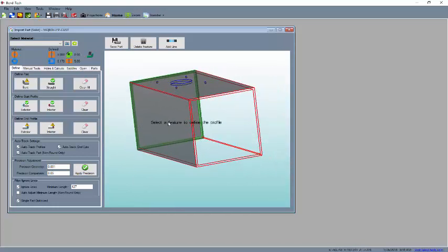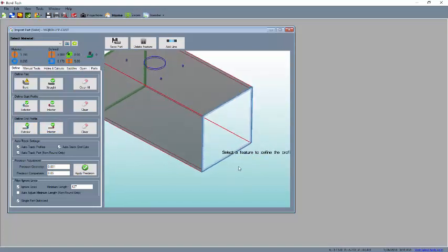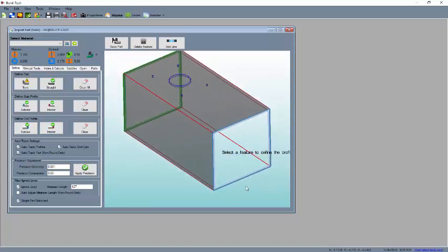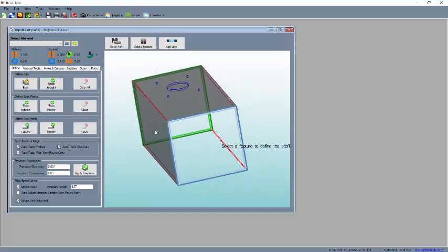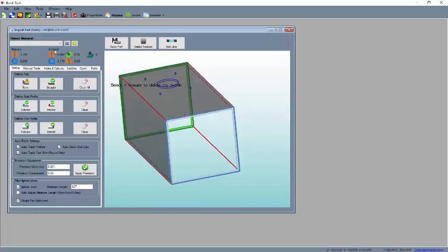Of course, it didn't do the end cut profile, so we'll do that manually. Just click exterior and then click an exterior line. Same with interior line. Typically, that's all you would need to define this part. Like I said, it will need corner radiuses on the corners. Otherwise, if I click plus here, it actually identifies this as a 5-inch round. So our importer is being worked on, obviously, but it's always improving. But that's the general process.